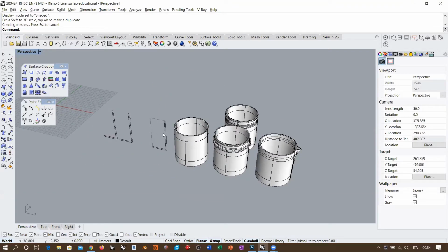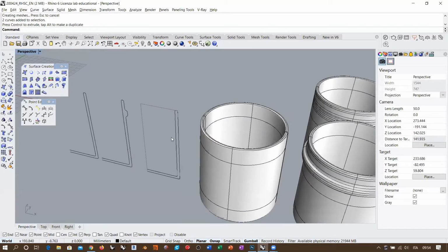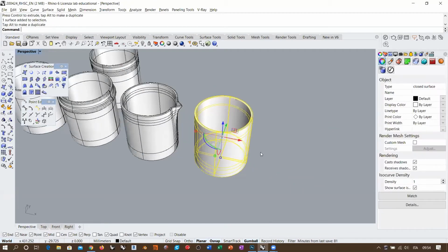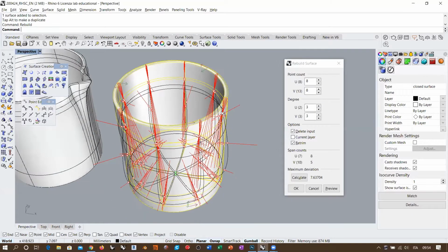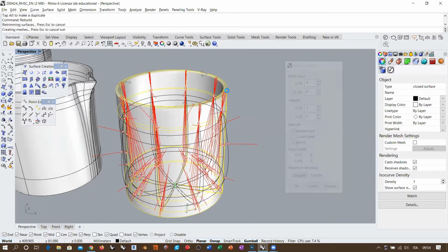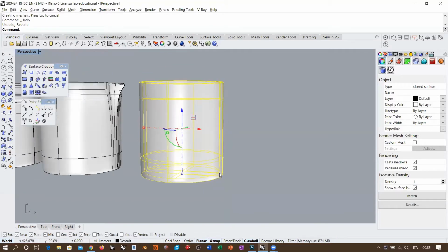You see that I never recommend rebuilding things as first option, because rebuild is a dramatic operation. Okay, so of course I can take the original surface that comes out from the standard rail flowing along the circle, like copying this, and I can rebuild this surface. Now, of course, in order to maintain this particular shape, which has no creases, it is perfectly smooth, but it has very sharp roundings here at the top, okay? And also we have 90 degrees here at the bottom, more or less.